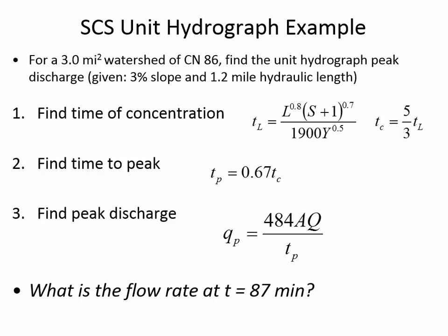Doesn't say that, does it? Find the unit hydrograph. Yeah, so unit hydrograph. Q equals 1 inch of rainfall excess. Okay, so we just put 1 inch, and then divided by the time to peak, 0.729 hours.